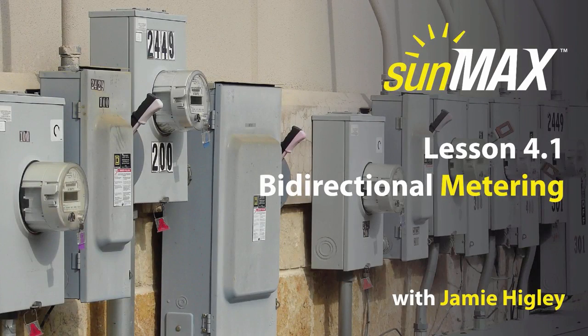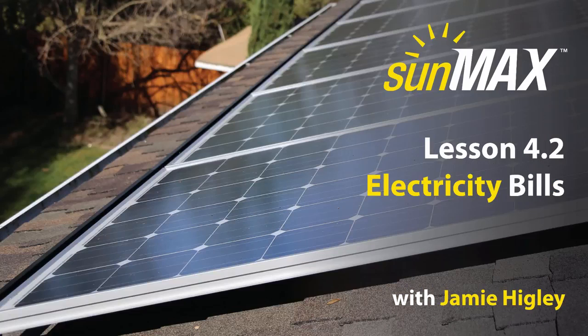When commissioning a grid-tied PV system, make sure that bidirectional metering is installed at the customer premise, so the customer actually receives credit for their system's energy production.